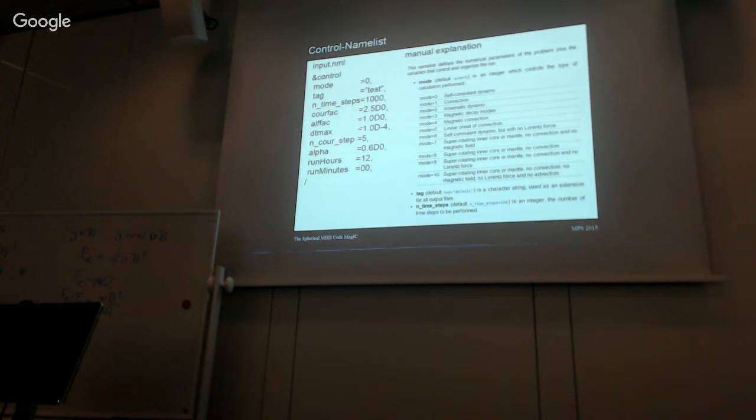Can you read that? I don't know. No, not so good. So definitely your time step needs to be smaller. You will have to resolve this effective time step, right? And that's basically formulated by the Courant-Friedrichs-Lewy criterion.